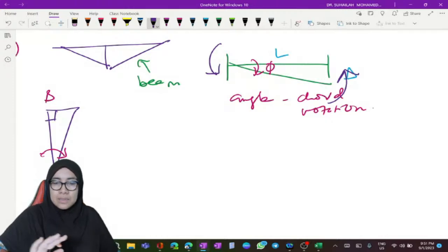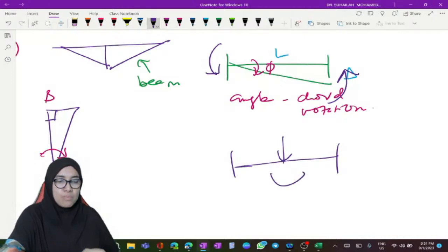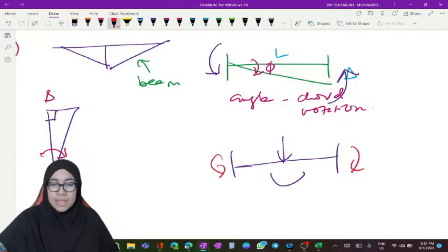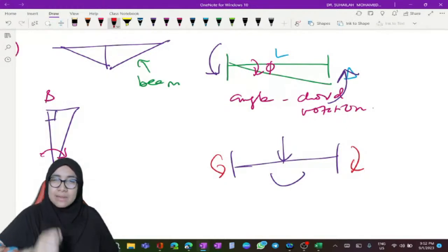It is different from a beam subjected to external loading, where the moment will be like this. However, in support settlement or Sidesway, due to delta, the fixed end moment is about behavior, so we have to look at the behavior after Sidesway or settlement occurs.